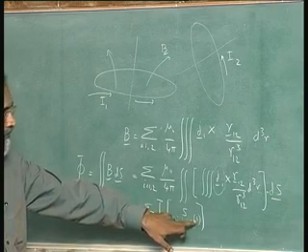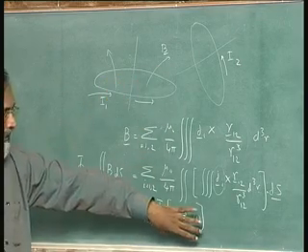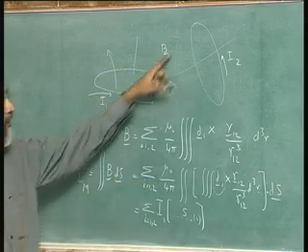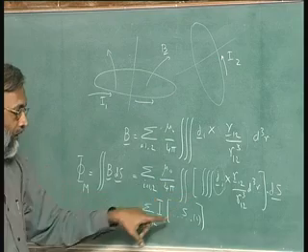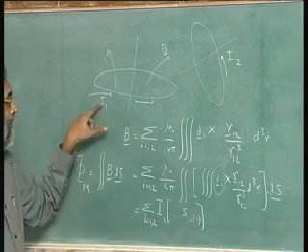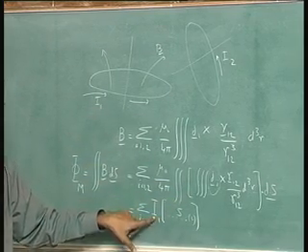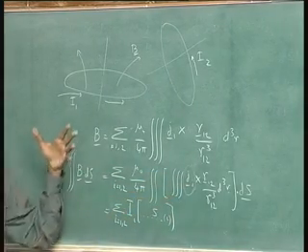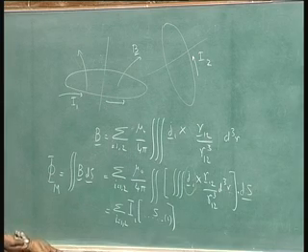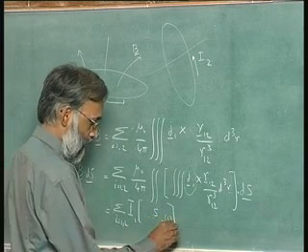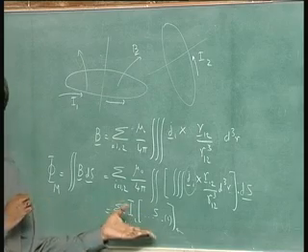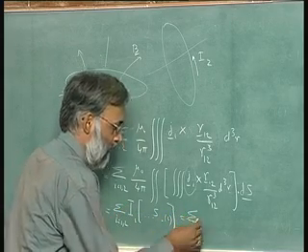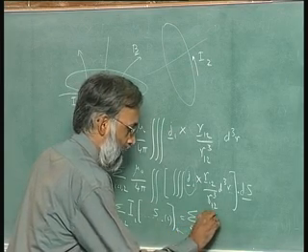As long as the coil shape does not change, this bracket does not change, because it depends only on how the coil goes around in space. The amplitude of the current comes through I_i. This is the result for unit current, and this is the result for changing that unit current into its actual value, which means I can write this whole thing as a coefficient, a number. So, I write this as some phi_i equals some C_i times I_i.